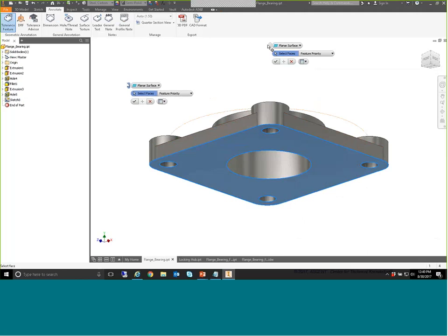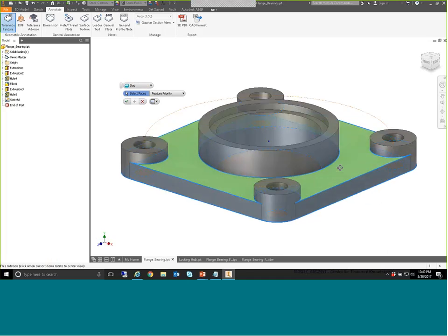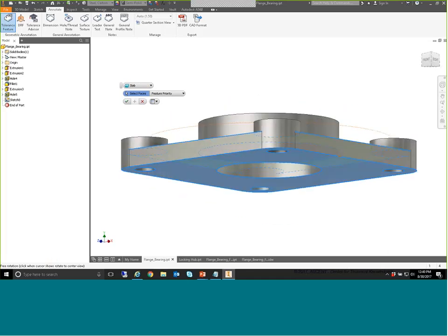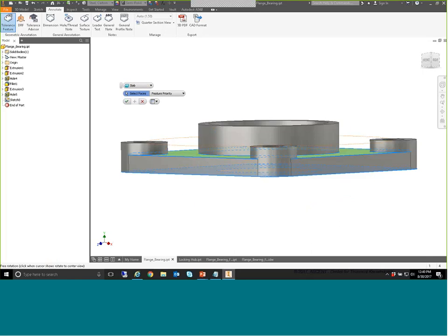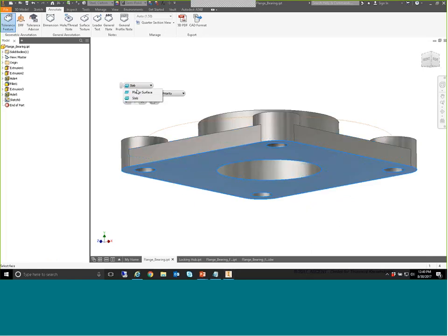And my mini toolbar appears, you can see. And it's knowing that I want to create a planar surface annotation based on the reference selection I made. I can pull that down. So let's say the assumption wasn't correct and I actually wanted to create it as a slab. You can see how it then grabs the parallel surface above it to reference. I don't actually want that. I actually do want a planar surface. I'm going to go back and leave that on and click OK.